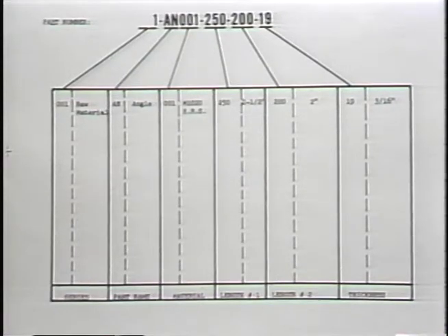And if you have a series of different dimensions, you have to indicate what the dimensions are from the lowest to the highest. Because if you don't have the lowest to the highest, which are the parameters, then people may develop part numbers that have lower dimensions or higher dimensions that is not an integral part of your part number program, and you're going to develop erroneous part numbers.